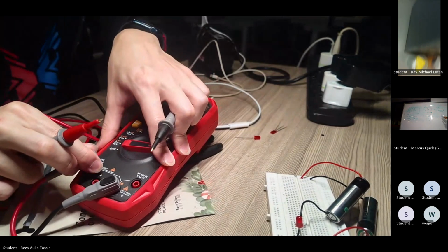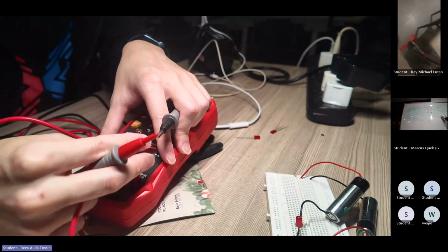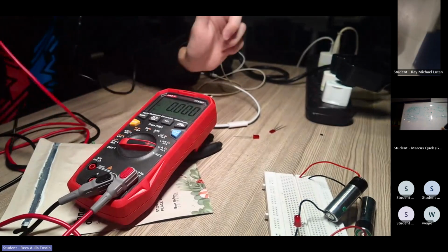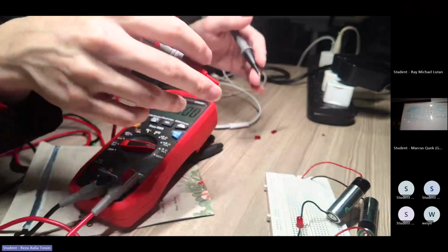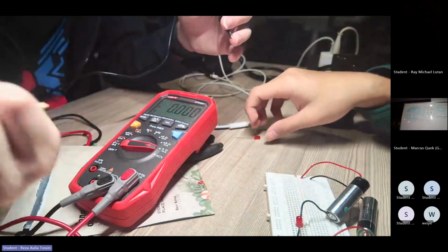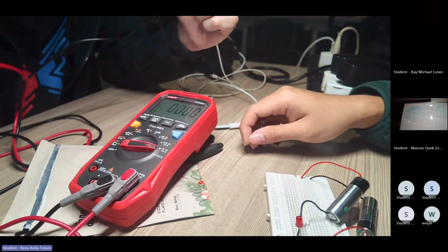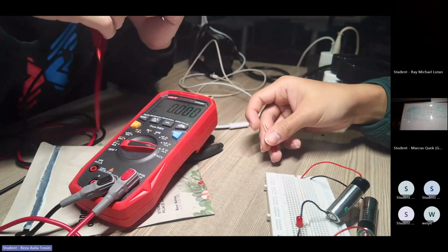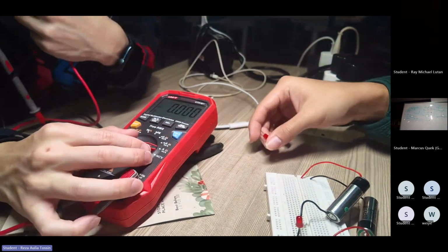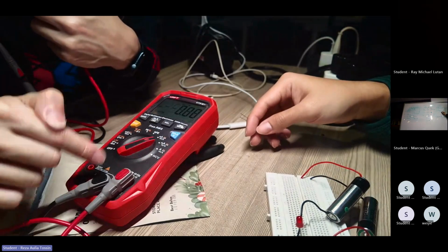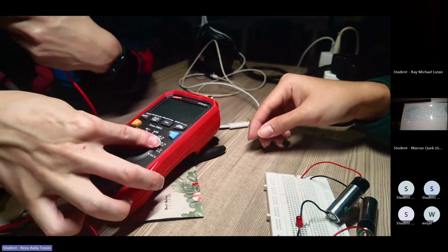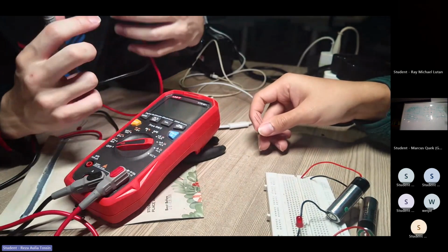All right. So a voltmeter goes in parallel across whatever you're measuring, and an ammeter goes in series with what you're measuring, because current flows through. So remember to choose the range. Remember to set the mode. That's all for multimeters. Everything else is like nobody cares.